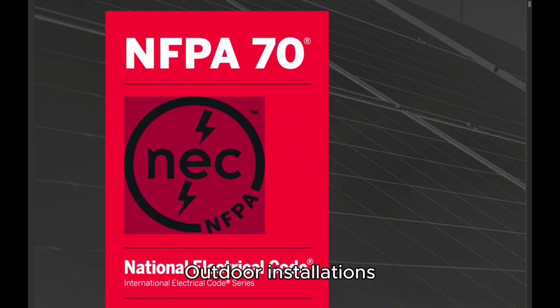2. Outdoor. Outdoor installations shall comply with 110.26(E)(2)(a) through (c). A. Installation requirements. Outdoor electrical equipment shall be installed in suitable enclosures and shall be protected from accidental contact by unauthorized personnel, or by vehicular traffic, or by accidental spillage or leakage from piping systems. B. Dedicated equipment space. The space equal to the width and depth of the equipment, and extending from grade to a height of 1.8 meters (6 feet) above the equipment, shall be dedicated to the electrical installation. No piping or other equipment foreign to the electrical installation shall be located in this zone. F. Locked electrical equipment rooms or enclosures. Electrical equipment rooms or enclosures housing electrical apparatus that are controlled by a lock(s) shall be considered accessible to qualified persons.